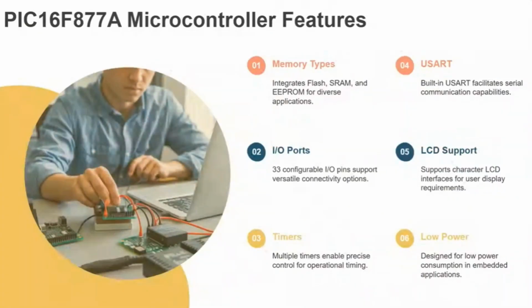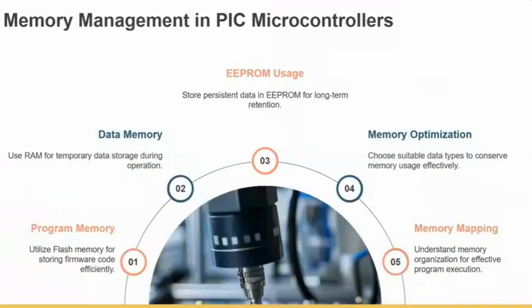The PIC 16F877A microcontroller features memory types such as static RAM, EEPROM, etc. It has 33 input output pins, multiple timers for operation timing, a universal synchronous asynchronous receiver transmitter, which is USART, and LCD support. It is designed for low power embedded applications.